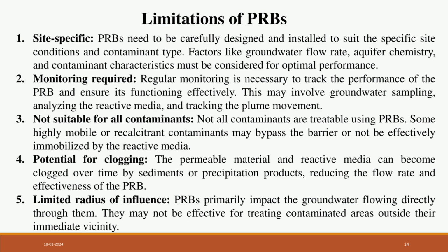Second one is monitoring required. Regular monitoring is necessary to track the performance of the PRB and ensure it is functioning effectively. This may involve groundwater sampling, analyzing the reactive media, and tracking the plume movement.